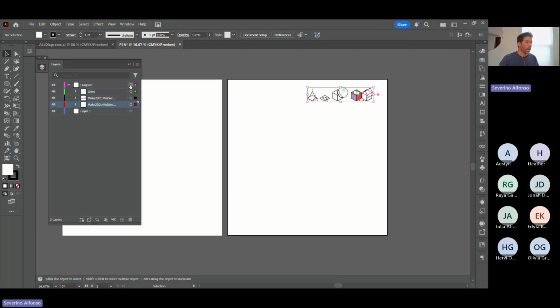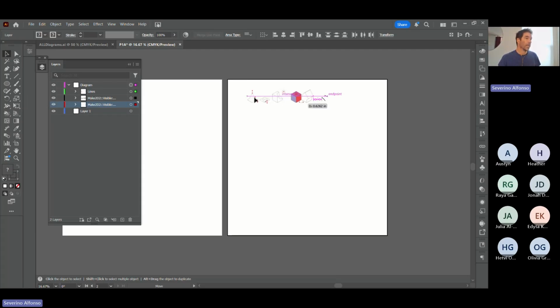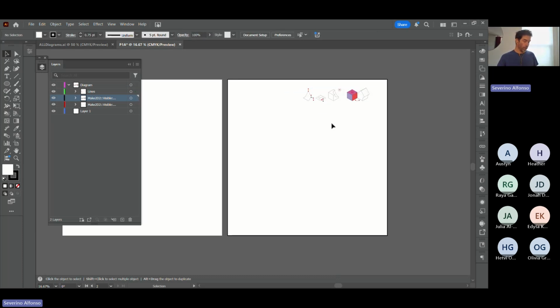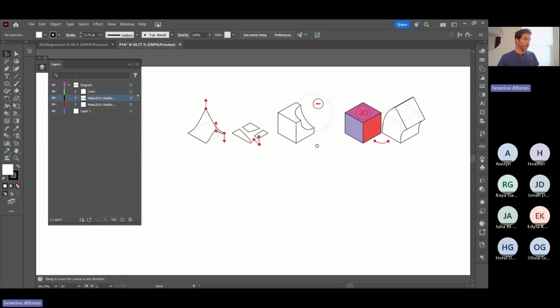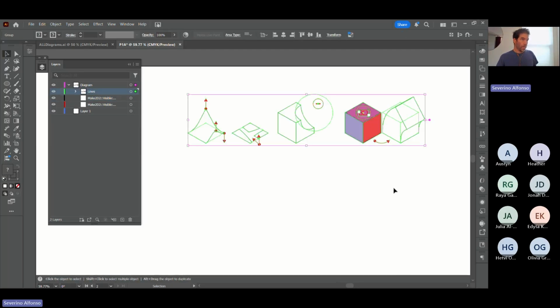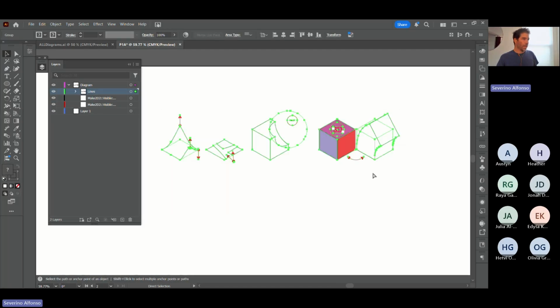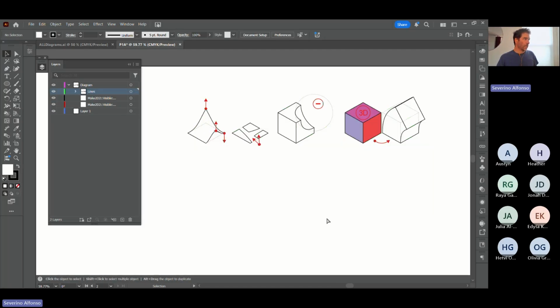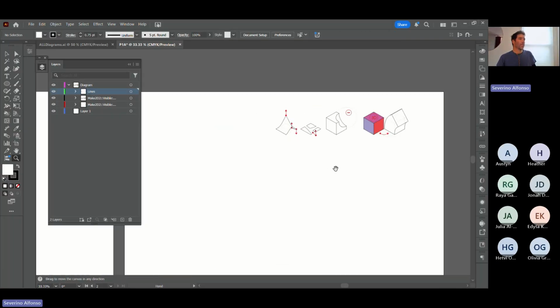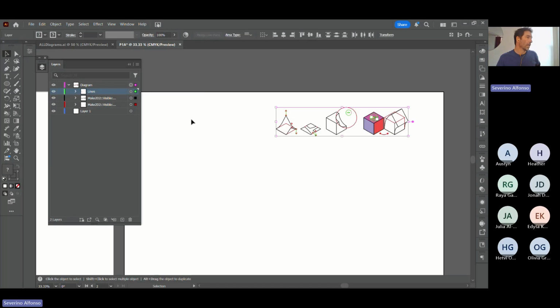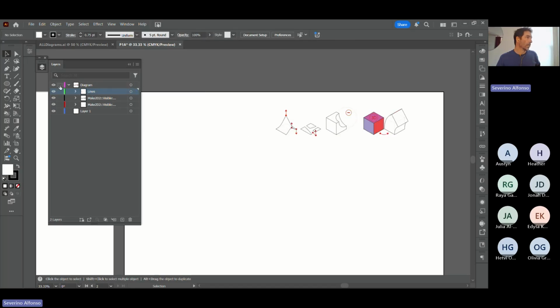That way you can select everything by clicking on the main layer and then move it around, or you can select parts of a layer. I think this is useful to be able to select groups without having to group. You can group things, select stuff, Control G, but it's not the same thing. It groups everything under one sublayer. So I'm not a fan of groups unless they're within the same layer. I like sublayering and being able to select the layer, because you can then lock the main layer altogether.